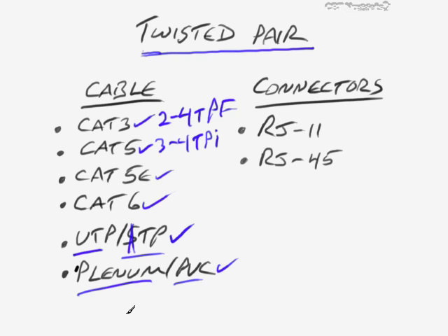This is where, if you are running the cable maybe up in the lights or something like that, let's say a fire starts up there, electrical short, whatever, when it burns the outer jacket of your twisted pair cabling, PVC can emit noxious fumes. That's generally not considered a good thing in the workplace. We don't really like to suck in that kind of air. So the plenum rated will be more expensive, of course, but it's guaranteed that it will not emit those same noxious fumes. Hence the plenum rating.